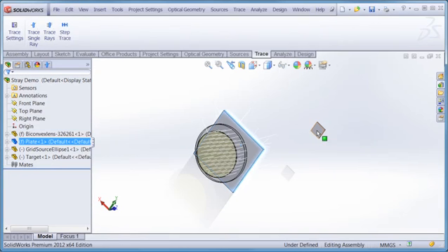When I'm doing a stray light analysis, I want to be able to isolate that data to show me the energy that can possibly reach one of my regions of interest, and more importantly, give me an idea of the paths that are available to reach that surface, and the most important item is exactly how much energy of that scattered light can actually reach my surface of interest.